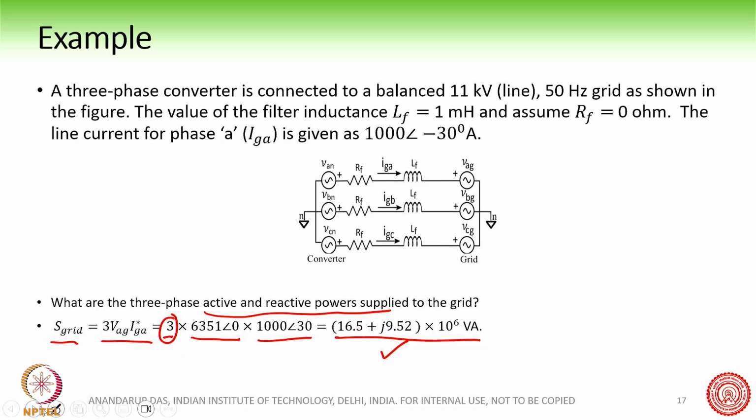So yeah, this is the end. Today we studied the steady state operation of the voltage source converter, and we understood that with a stiff DC link or a battery, the voltage source converter is basically a four-quadrant converter, and it can exchange P and Q as we command it.